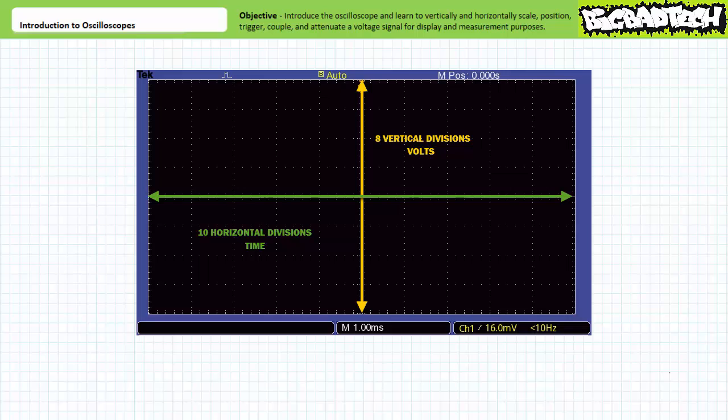Note the horizontal axis typically runs right through the middle of the screen. However, one can independently position this up or down, as we'll learn in a moment. Given time-variant voltage forms can swap polarity many times a second at speeds beyond human perception, the oscope's ability to capture these waveforms allows a human operator to visualize this phenomenon. Additionally, an operator can zoom in or out to the required scale and make a desired measurement on the waveform under inspection by adjusting the value of each vertical or horizontal division.